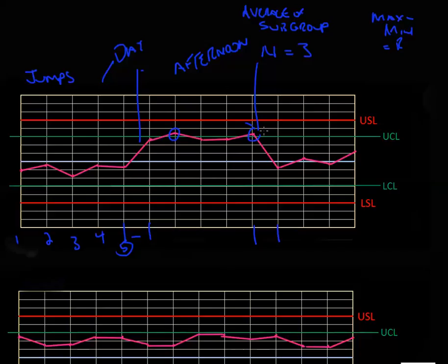Maybe this is a sub-assembly operation, and you have non-homogeneous data. In other words, this isn't a continuous flow of data, but this might be one batch of material, and then this is a second batch of material that processes differently. You see that in, for instance, plastic injection molding. You see that in forging, all sorts of applications where maybe the raw material shifted and that wasn't noted on the chart.